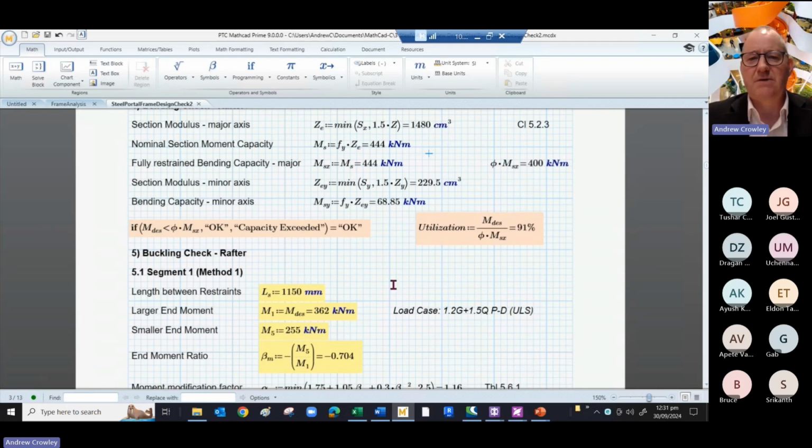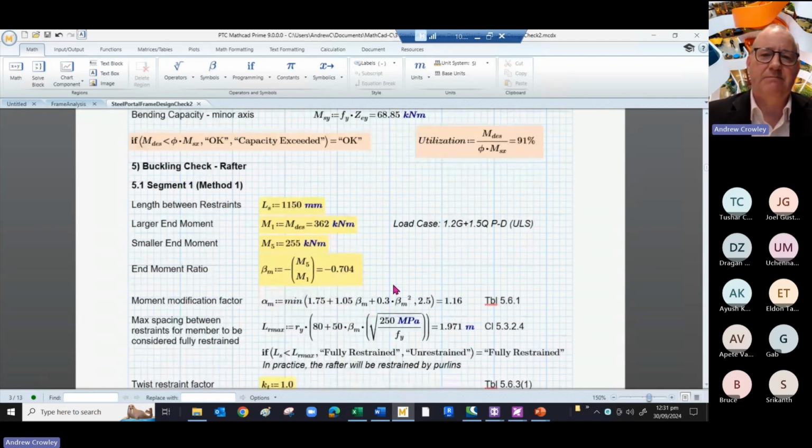And that'll save you the time for the rest of this, because the rest of it gets a lot more complicated. So we're looking at buckling, and it's buckling about the minor axis. Your major axis capacity for a rafter depends upon the buckling about the minor axis, and the minor axis is restrained along the length of your rafter. So you've got a 20-meter long rafter, but you want to divide it up. Conveniently, we have purlins at regular intervals, and the little trick is to double or halve the space between the purlins at the eaves and the apex, and that halves the effective length that's unrestrained.